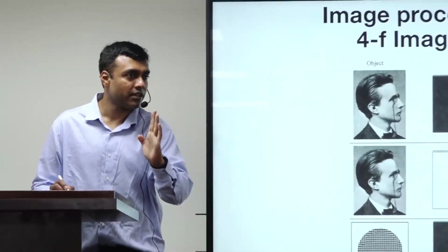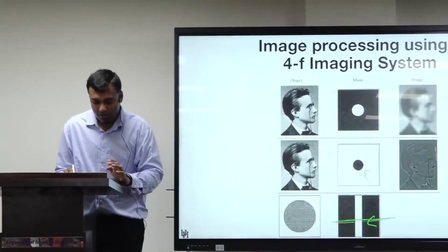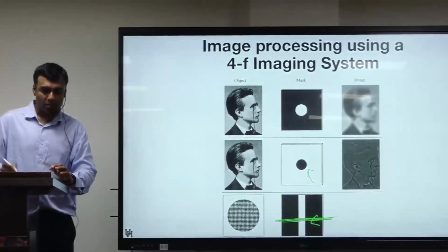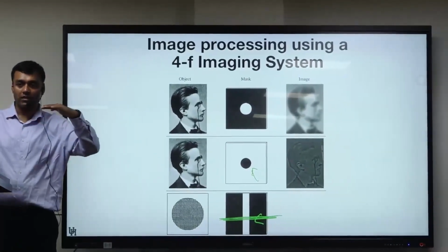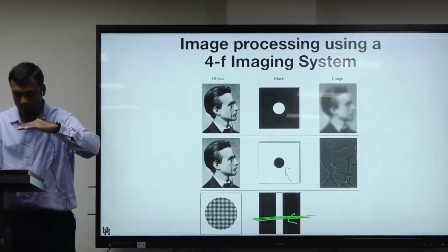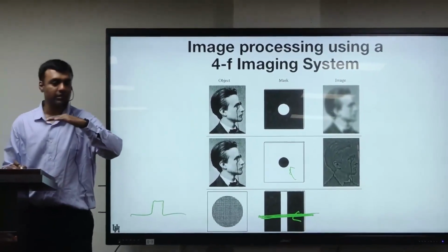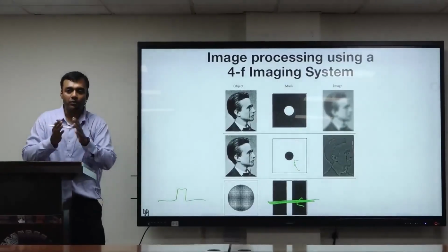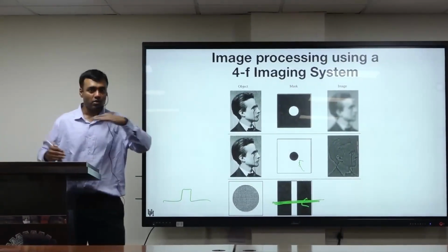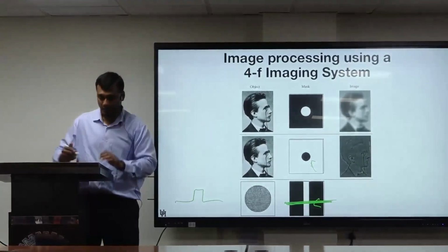Unlike here where it's circularly symmetric, here it is different along the x direction and the y direction. If you look at the horizontal direction, it's a low pass filter along the horizontal axis. If you draw a line like this, it looks something like this, right? It's keeping low frequencies, removing high frequencies. So horizontally, it's a low pass filter.